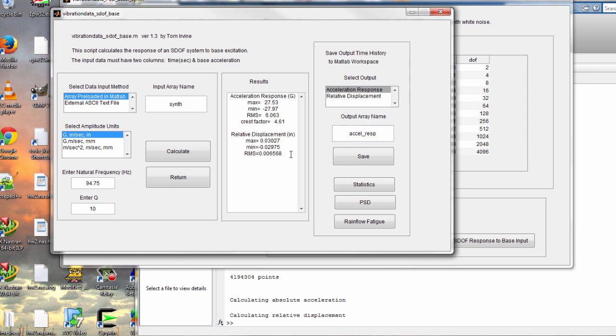Now here's something that has always concerned me, and we've talked about this before: if we take the ratio of the peak absolute value to the RMS, that gives us our crest factor. You could think about RMS being equivalent to the 1 sigma value, assuming a zero mean.